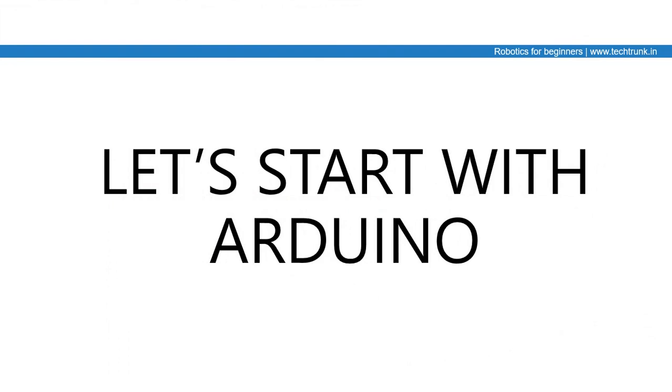Next, now let's start with Arduinos. Arduinos are development boards which use microcontroller families of AVR, and based on that it customizes the use of microcontrollers in a simple manner so that it is very simple to use for designing small scale programmable systems. So Arduinos are a series of boards with microcontrollers on board, mostly AVR series microcontrollers, and can be used as ready-to-use programmable systems. Arduinos are not a microcontroller, Arduinos are not ICs, they are development circuit boards which use AVR series microcontrollers for programming. And Arduinos are open source boards, designed to be very easy to use.